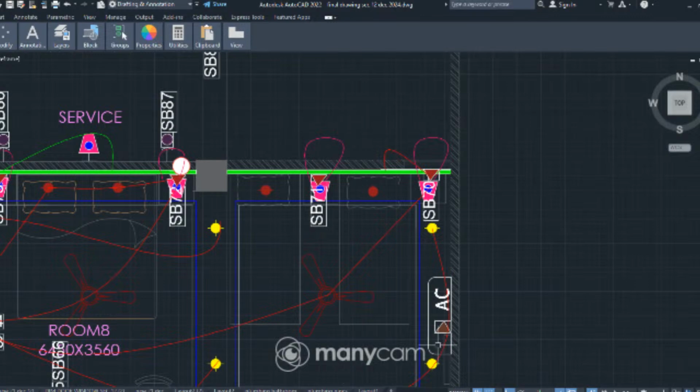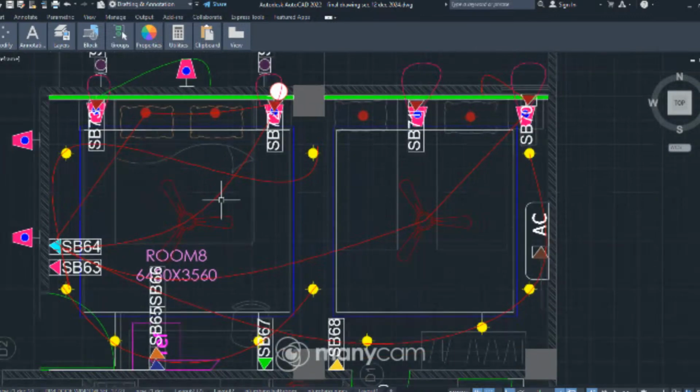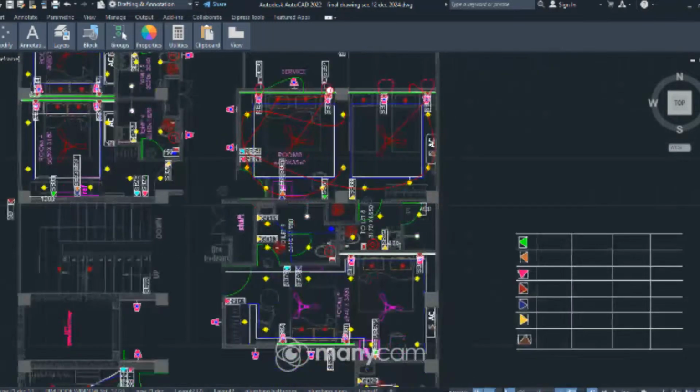We can also do one thing. We can just provide the fan switch here to the side table, and we can just avoid a two-way light, two-way, because that will make it easier, else a person gets confused with the fans. We'll remove it. We just make single way.